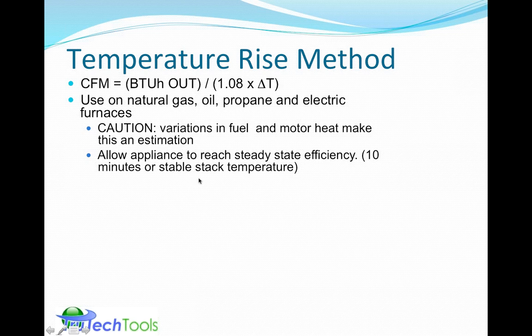And you do also have to wait for the appliance to reach a steady state efficiency level, which may take up to 10 minutes or so, or just checking to see that you've achieved that stable stack temperature in order to get this type of measurement.